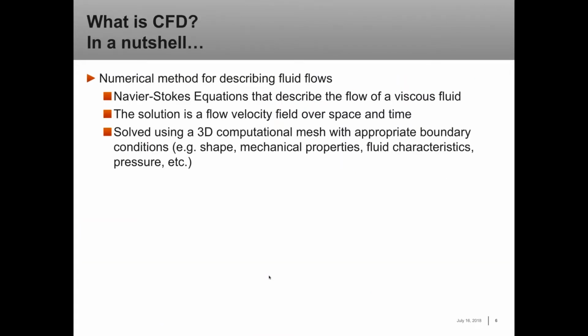So what is CFD modeling, computational fluid dynamics? Well, basically, it's a numerical method for describing fluid flows. The Navier-Stokes equations form the basis for these calculations, and they describe the flow of a viscous fluid, which in this case is going to be air for the respiratory system. The solution is generally a flow velocity field over space and time, and it's this velocity field that is carrying materials throughout the airspace and over the course of the simulation.